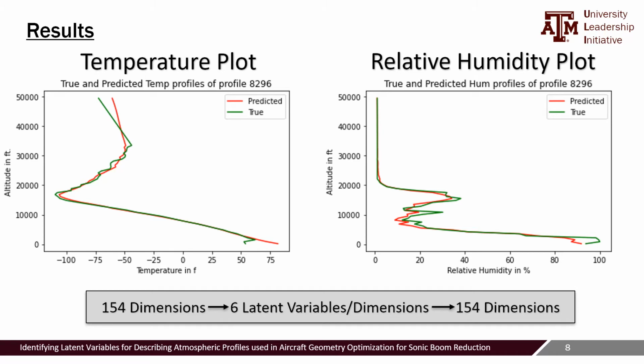One way to address this problem is by running these predicted profiles through S-boom and PYLDB, which are algorithms that propagate a sonic boom through a given atmosphere and produce a perceived loudness value. If the perceived loudness value is close to the true profile perceived loudness value, then this can be an indicator that the predicted profile may still be valid, though it may not visually seem so.